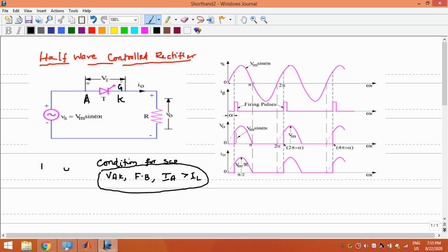So at this instant, say omega t is equal to 0, the SCR is ready for conduction, but it waits for the triggering angle, which is here given as the firing angle delay of say alpha degree. Let us take alpha equal to 45 degree. So you are turning on this thyristor after 45 degree. Once the triggering pulse at 45 degree is given, the SCR acts like a short circuit conductor. So the switch is on at alpha equal to 45 degree.